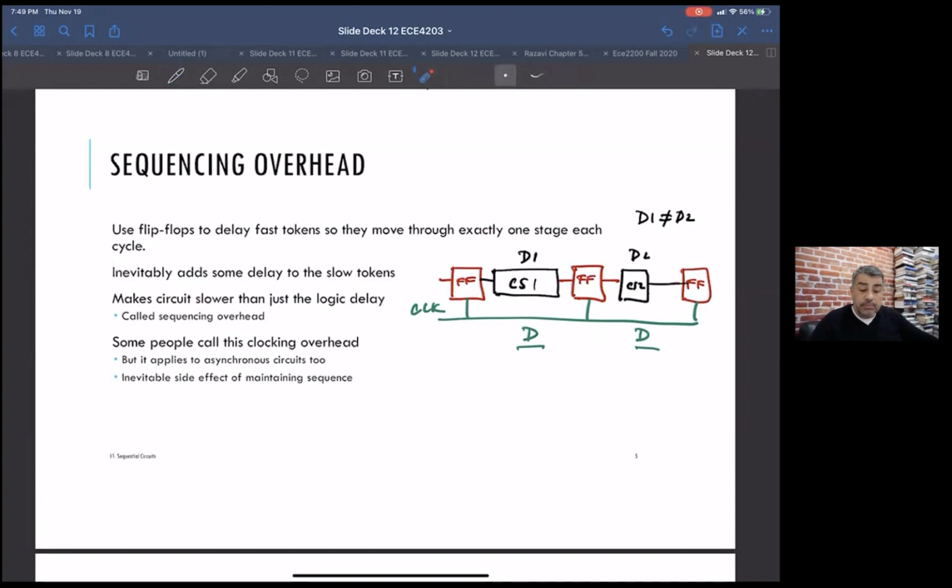Taking us one step back, your clock determines your minimum clock speed or maximum clock period, which decides what the longest delay could be between stages. Everybody then has to wait for that delay to happen to get to the next stage.